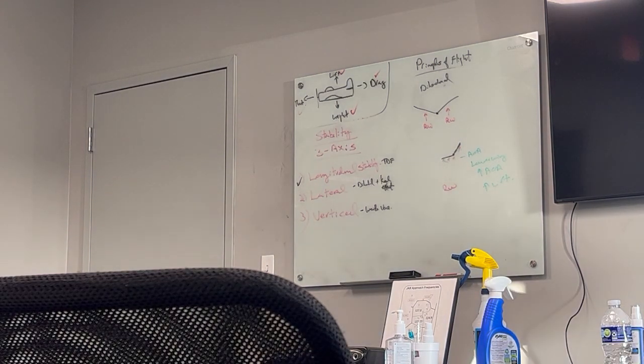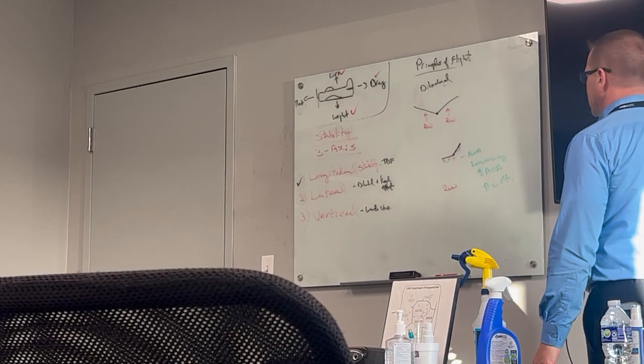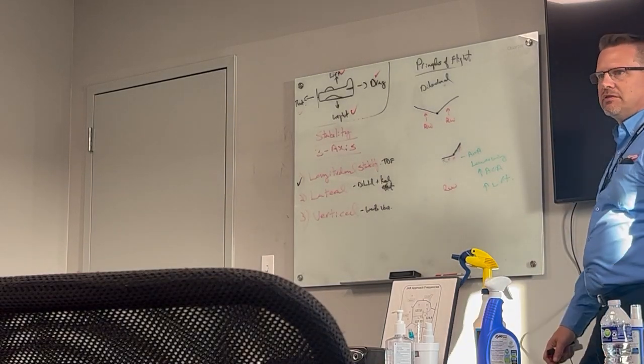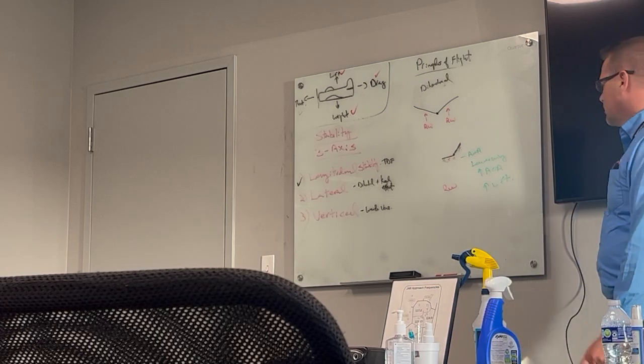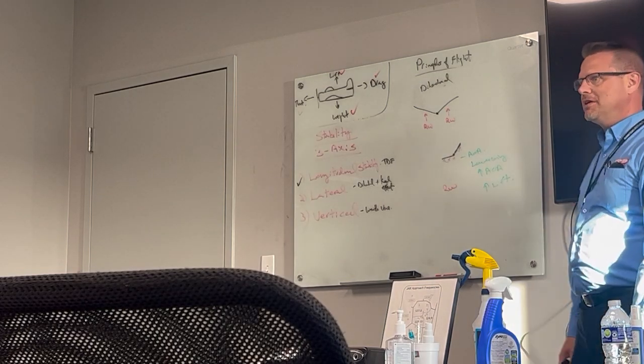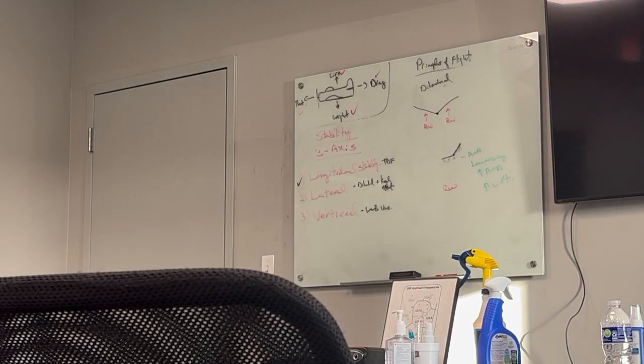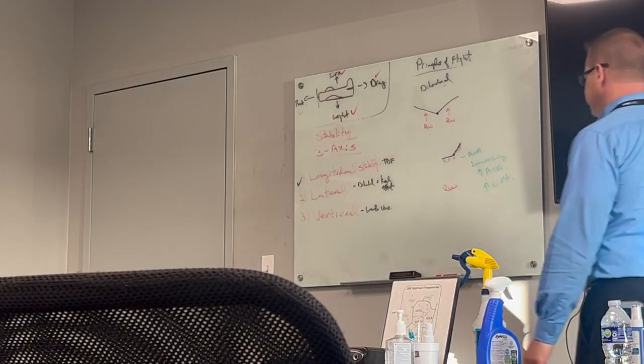Based on the fact that the dihedral of this aircraft is built in, we have it specifically for that reason, for stability. You want to be less stable and have more controllability, take out the dihedral. Just have a flat wing, no dihedral. Then you can have aerobatic.